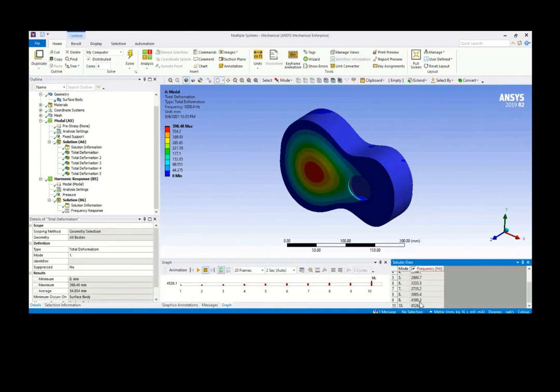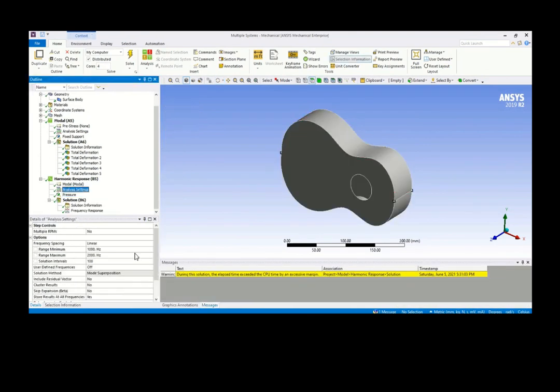Of course, you can go up to 4000 to see the effect of the natural frequencies with the excitation frequency, up to 8 modes. Here I'm just looking into 2 modes. The example states 1000 to 4000 with 300 solution intervals, so you have to wait 3 times longer, but now I'm using just up to 100.